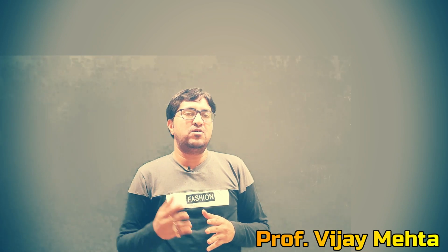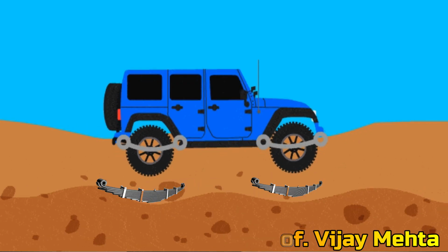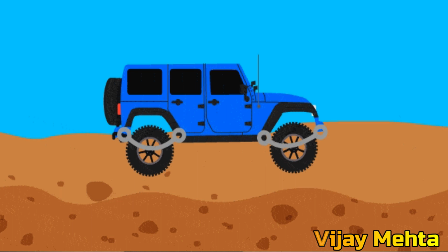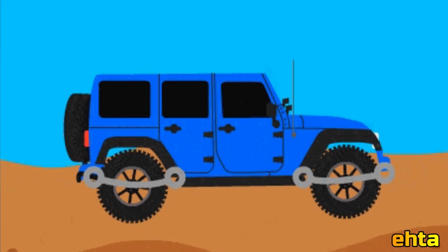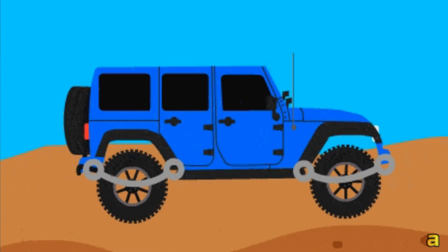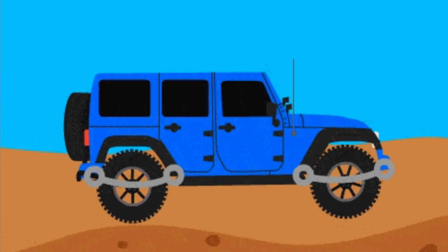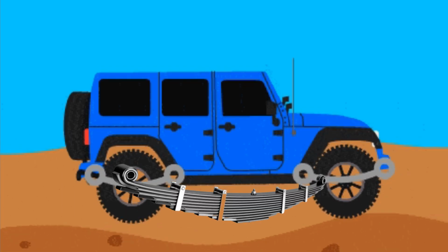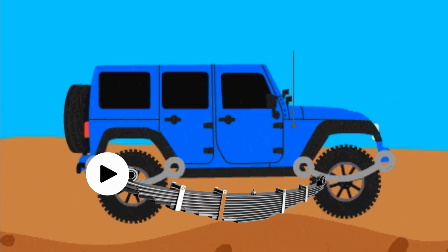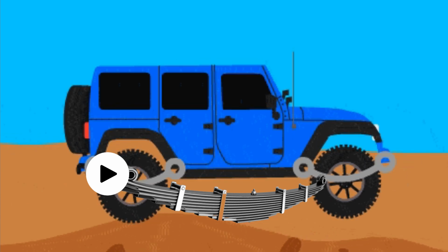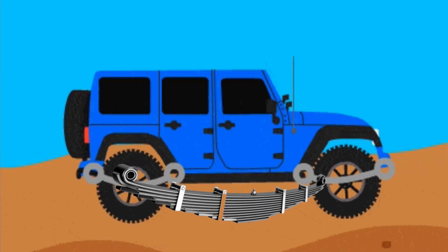In a heavy loaded vehicle, the leaf spring is longer on the rear side and smaller in length on the front side, because of a different frequency of vibration, so your vehicle will not bounce more. It will vibrate at different frequencies, which prevents excessive bounce. The spring eyes of heavy vehicles are usually bushed with phosphorus bronze bushes.